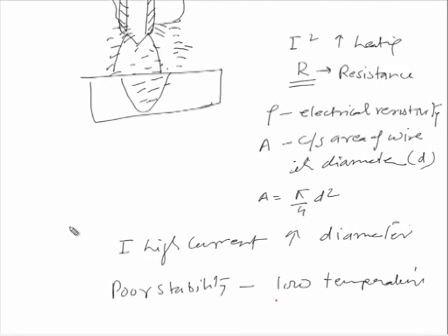So, the level of welding current which allows a smooth and stable arc is found suitable for welding purposes. The lower level of the welding current is mainly limited by the arc stability. Here we need to select the welding current in such a way that the required heat is generated continuously, and the arc is also stable, so that the heat generation can be effectively used for melting the faying surfaces.